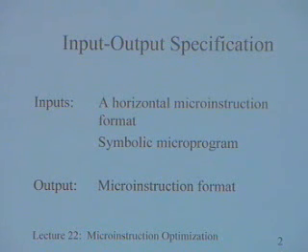Remember, we discussed in the last class that we can either optimize the microinstruction word length based on the architecture, or we can optimize it for the application. In this case we are talking of optimizing for the application. Of course, optimizing for the architecture is a problem subset, in the sense that typically it will be much easier to find the set of disjoint control signals by analyzing the architecture. So we are not considering that problem. Of course, you can apply the same techniques we are developing here to that situation as well.